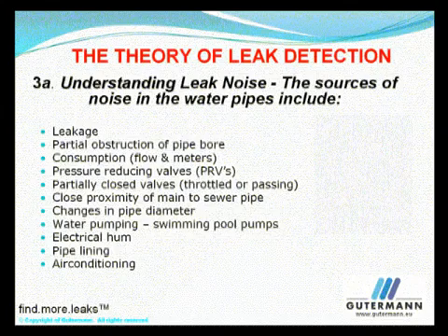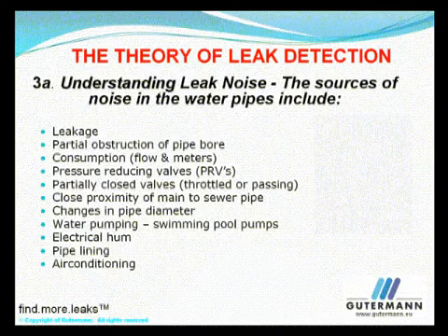Leak noises. To be a good leakage operator, we need to recognize all the different types of noises in the pipes so we can take the appropriate action. The typical sounds are leakage, which is usually a high-frequency whistling sound; flow, a low-frequency droning sound; obstructions and insertion probes, usually a more intense flow sound; consumption through a water meter, a mid-frequency running water sound, not too different from a leak, but with a ticking sound as the wheel of the meter rotates.